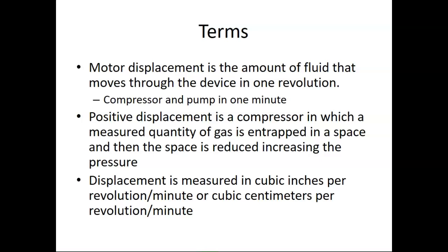So positive displacement is a compressor in which the gas is entrapped in a space and the space is reduced, increasing the pressure. In other words, if you take a bottle and start trying to crush it, what have you done to the inside of the bottle? You've increased the air pressure, right? The pressure has increased inside the bottle. Not always by a bunch, but by just enough that sometimes it can pop the cap off, right?